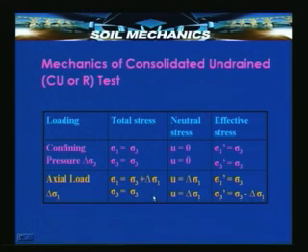The total stresses remain the same because the axial load gets applied as total stress. Now the water is not free of stress because undrained conditions prevail. U in water is delta sigma 1, the applied axial load, both in the horizontal direction and in the vertical direction, because the specimen is surrounded by water in a Perspex cylinder. But the effective stresses will be